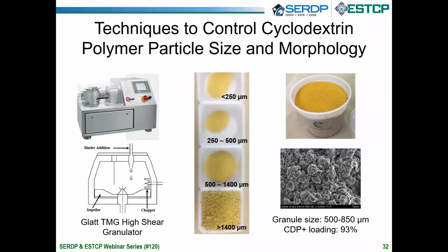Here I want to talk about our efforts to transform the as-synthesized powdered adsorbents into granular materials that are suitable for packed bed filtration processes. As part of this SERDP project, CycloPure has explored a variety of so-called granularization procedures. The approach that has shown the most promise is a spray granularization technique that combines the as-synthesized adsorbent powder with an FDA-approved binder material in a high-shear granulator.